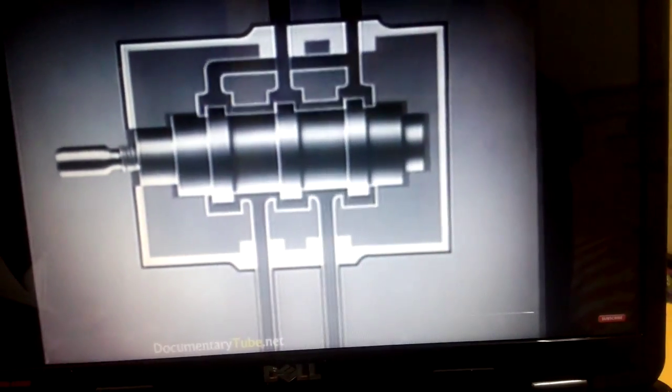Now the fluid enters from the relief valve into the upper pipes and then moves to the power cylinder like this. Now the extra fluid from the power cylinder comes back through the same pipes and then moves up like this. In this way, the control valve controls the movement of fluid, and there will never be an extra pressure in the power cylinder. And this then gives up and down movement to a steering shaft through splines. This up and down movement is then transferred to the wheels and hence helps in steering the wheels. Now I've shown you a basic hydraulic power steering system.